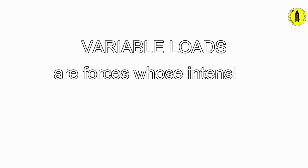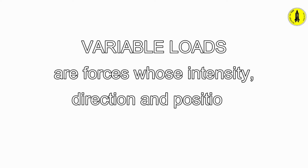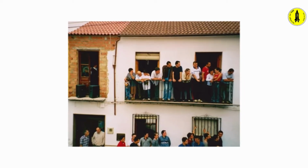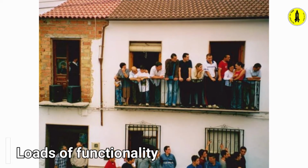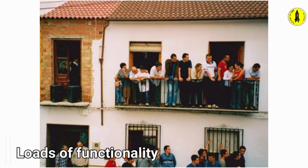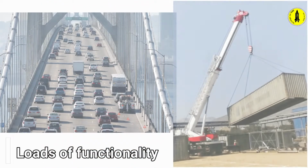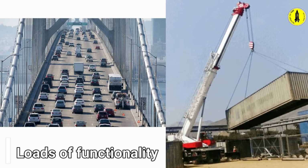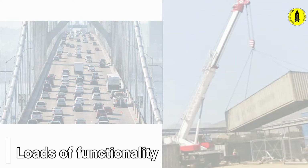Variable loads are forces whose intensity, direction, and position do change over time. We distinguish two subtypes. Loads of functionality. These are forces that act on the structure and are directly related to its main function. For example, the weight of cars on a bridge or the weight of this load on this crane.